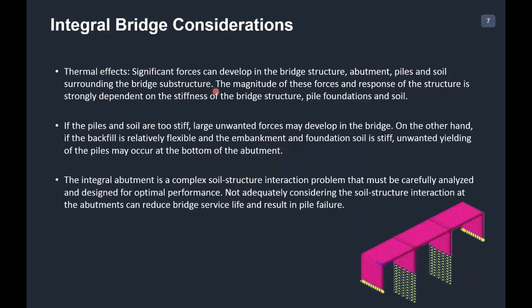The magnitude of these forces and the response of the structure is strongly dependent on the stiffness of the bridge structure and the foundation. Because of thermal effects, the whole behavior changes because of the deck being jointless and the substructure being monolithic. If the piles and the soil surrounding the abutments are too stiff, large unwanted forces may develop in the bridge. So you need to take care of this in the design.